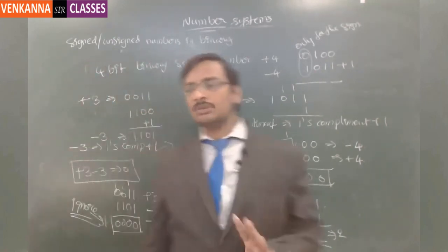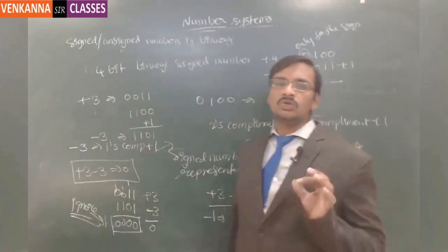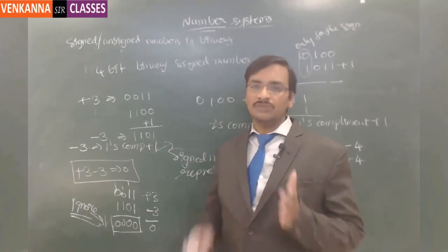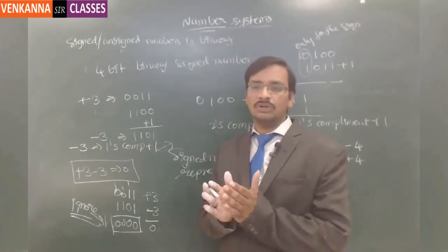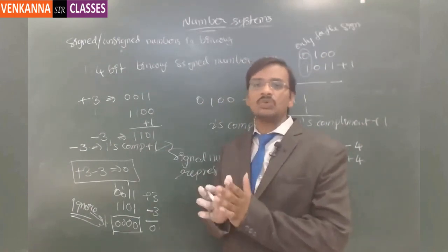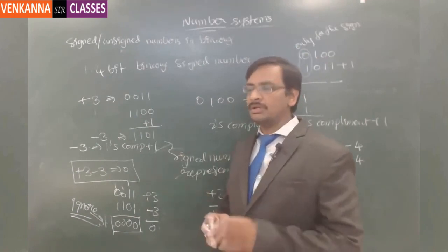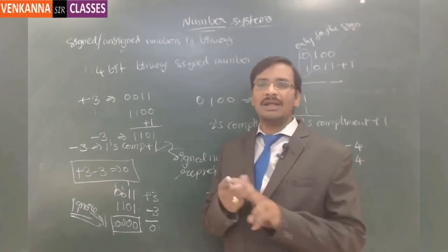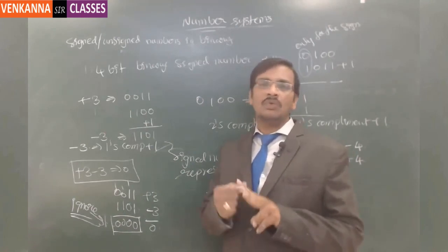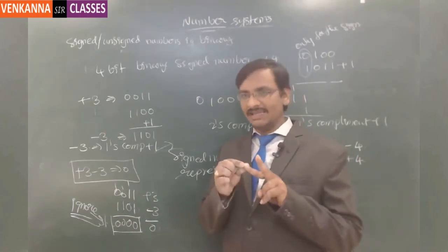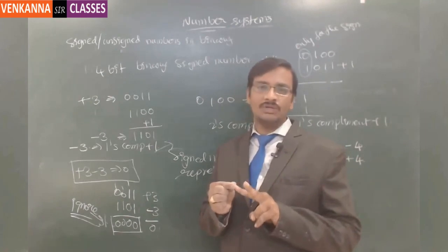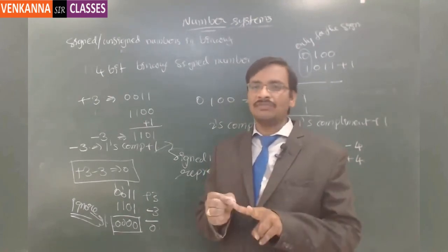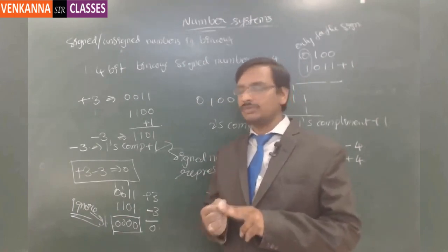So the main conclusion here is, usually when we are designing circuits, more or less we will try to generate one circuit and make use of that circuit to do the maximum number of operations. So we fundamentally get two different operations: one is the addition and another is the subtraction. So we will just design an adder which will add two different numbers, and then we will make use of that adder itself to do the subtraction also, in this manner.